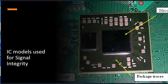In that case, the signal integrity engineer must have the knowledge to edit the model as per the requirement, and also use the proper voltage levels that are being used, and importantly, validate that model. That is very, very important. Before using it in the analysis, one has to validate the model.